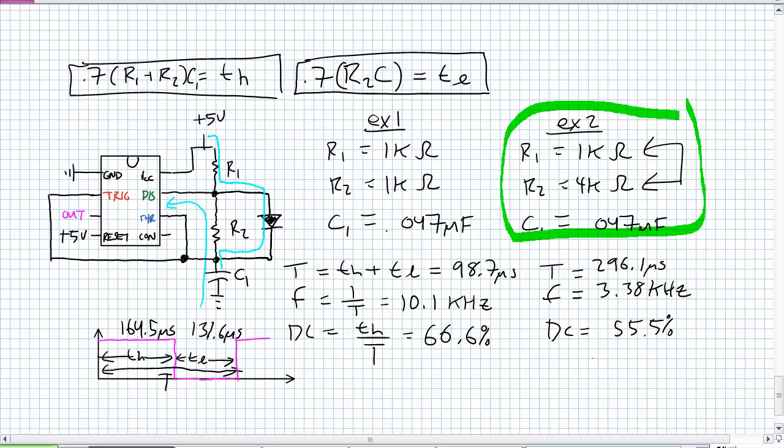What's going through that diode? My time constant for the charge configuration now is R1C1. Basically got rid of this guy. What is the discharge path? Well, the diode is reverse biased. It's still R2 and only R2. Again, this is a totally ideal magic diode that has no bias voltage across it.